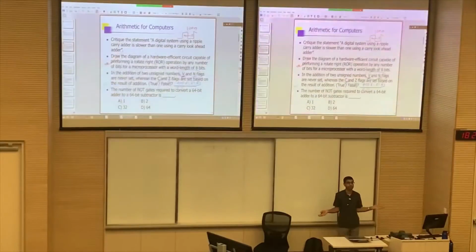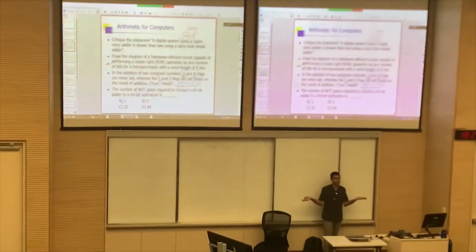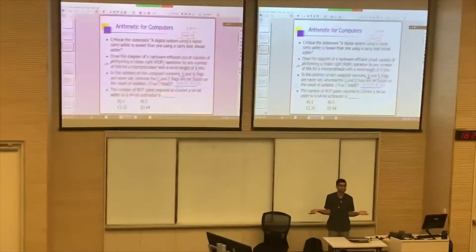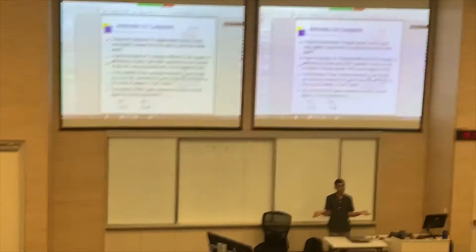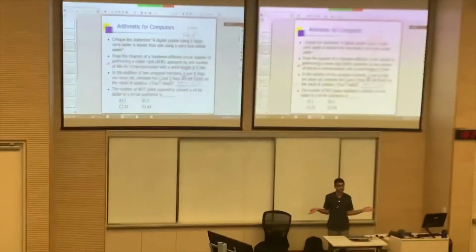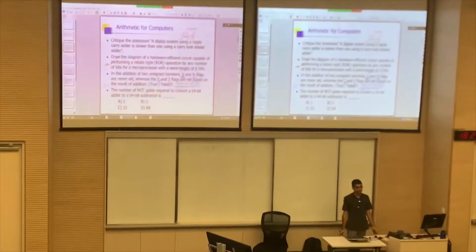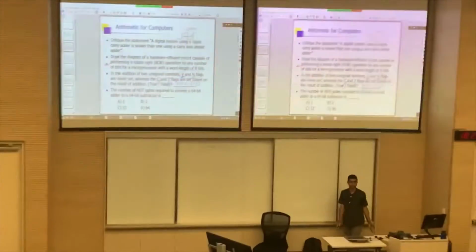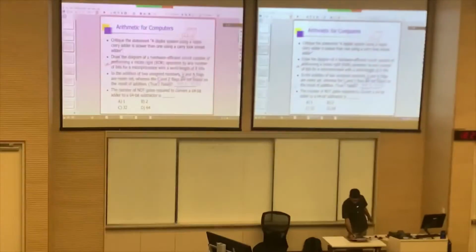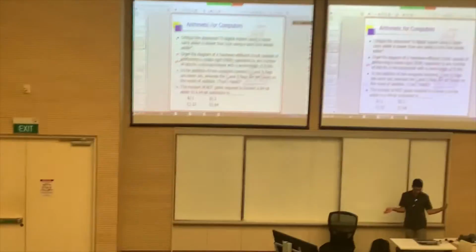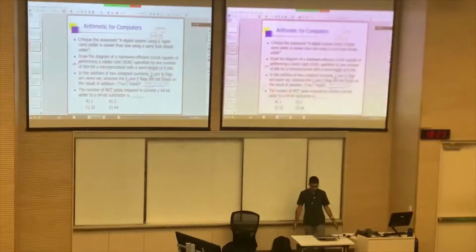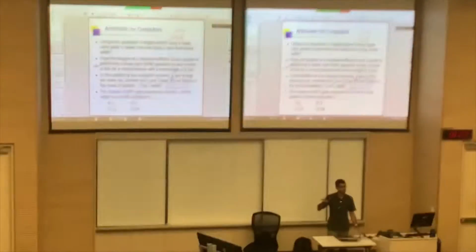Will the assembler complain? No, it doesn't, because it doesn't know whether you are dealing with signed or unsigned. Assembler does not do any kind of type checking, any kind of adjustment for you. The C compiler does, but in a rather weak fashion. But the assembler absolutely doesn't. It doesn't give you any kind of error or even a warning. So you will be doing it horribly wrong. Your results will be different from what you expect, especially in some circumstances. It actually might not show up if you are dealing with relatively small numbers.